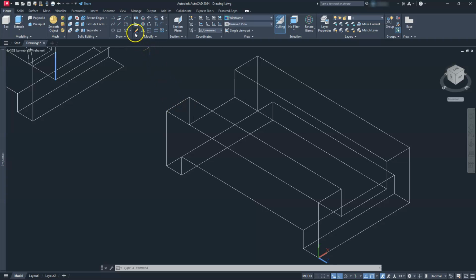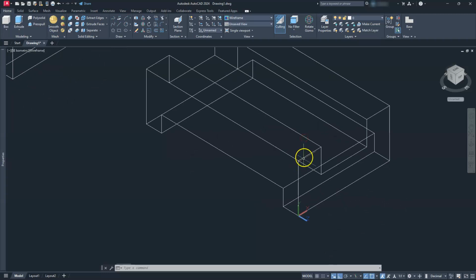All right, so what we're going to do is manipulate our UCS and get it right at that end point that's located here on the top. So I'll choose this 3 point, I'll go to this endpoint, the X direction, I want it to go this direction, so I'll left click here. The Y direction, I want to go up, so I'll left click here, and then it's set up, right? So now when I create my first point, I know that my circle is 25 units to the left. So therefore my first number should be a negative 25.